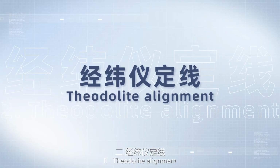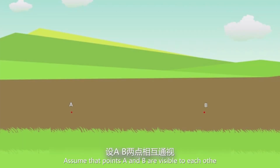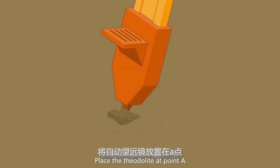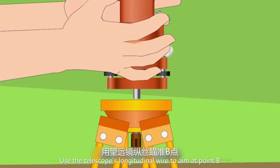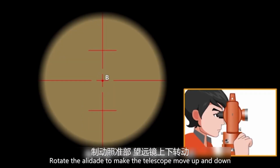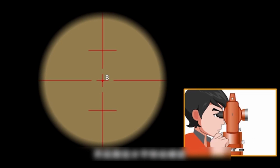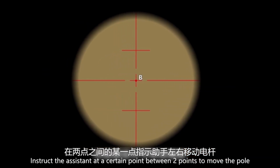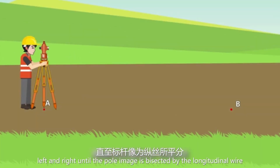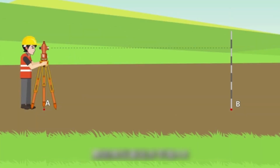2. Theodolite alignment. Assume that points A and B are visible to each other. Place the theodolite at point A, use the telescope's longitudinal wire to aim at point B, rotate the alidade to make the telescope move up and down. Instruct the assistant at a certain point between 2 points to move the pole left and right until the pole image is bisected by the longitudinal wire.